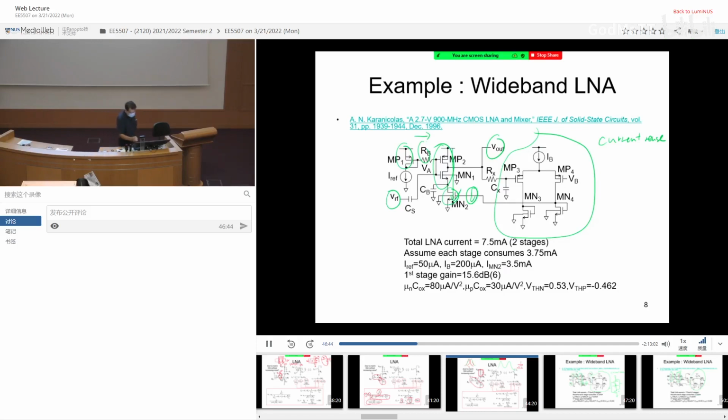So you are creating two common source amplifiers using a single current. Think about that. If you want a common source amplifier, usually you will do this kind of thing, right? There is a resistor here, there is another resistor here. Probably connect them together, and the outputs are joined together. But that will create two kinds of current. This will consume one current, this will consume another current.